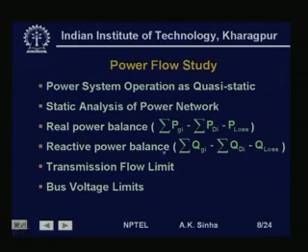Similarly, the reactive power balance equation also holds good, that is, the total reactive power generated by the generators or the transmission lines must be absorbed by the loads and the losses in the series element of the transmission lines. So, both real and reactive power balance equations hold good.